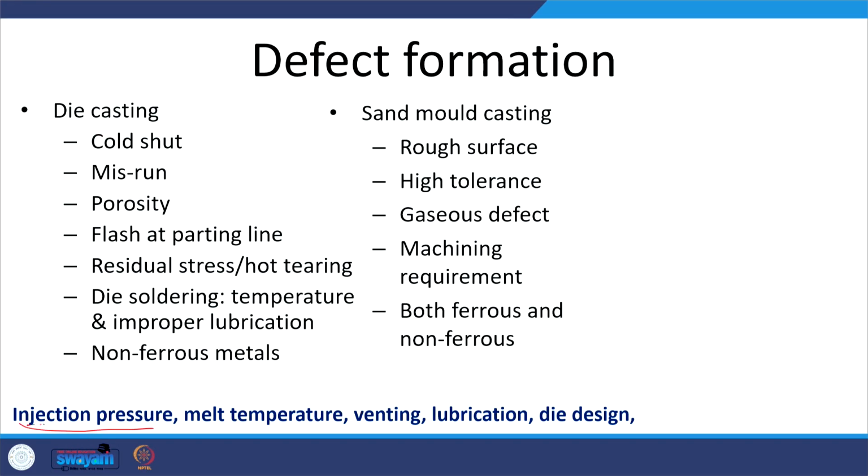So, here, if the injection pressure is less, then the flow rate will be slow and it will take a longer filling time, and that will promote cold shut and misrun. If the melt temperature is low, then this will again promote cold shut and misrun. If the venting is not proper, then this will promote gaseous defects in the casting, especially in the case of die casting. If the lubrication is not proper, then it will promote die soldering, and improper die design will promote tensile residual stresses and increased cracking tendency.